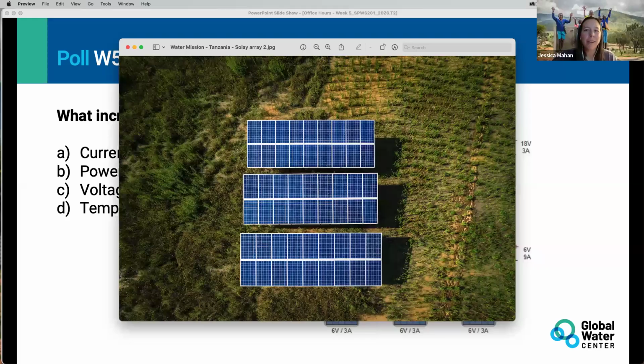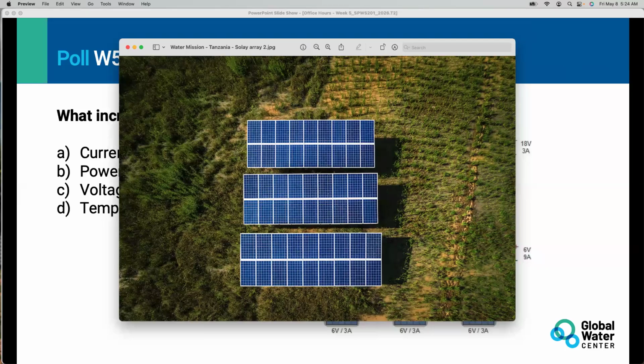Does that help, or do you have any follow-up or clarifications on that? Yeah, that's helpful. I was reviewing a design that we're about to start, and it was saying that we're going to have one string of 15 solar panels. And I'm just thinking about site arrangement and everything, that seems complicated, because I've seen more solar panel racks that end up in a square looking configuration, because you have roughly a similar amount in parallel versus series, but one string of 15 seems a little hectic to me. I mean, this is 9 with 2, but I was just curious about that.